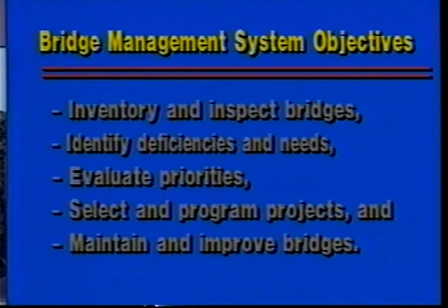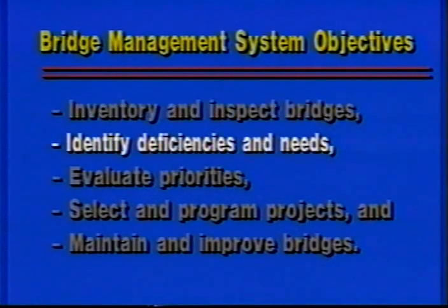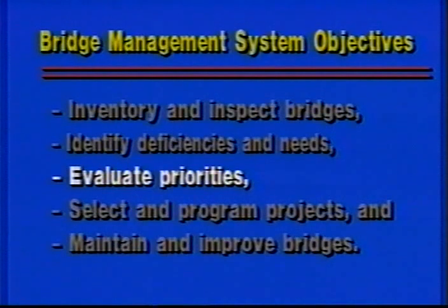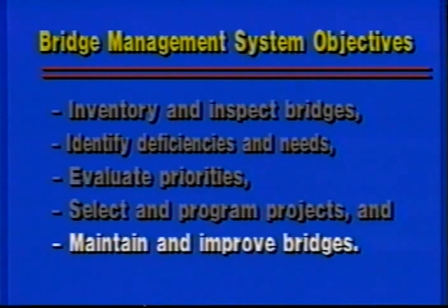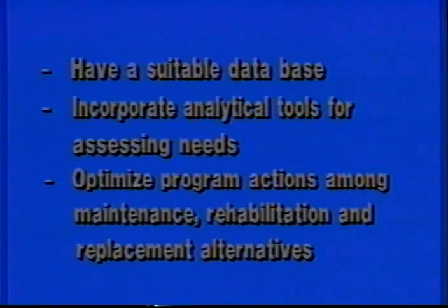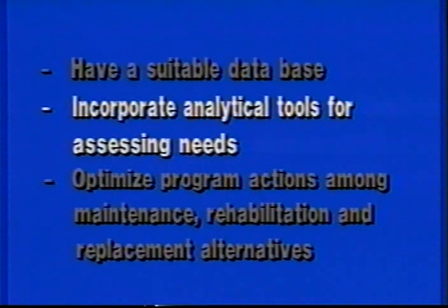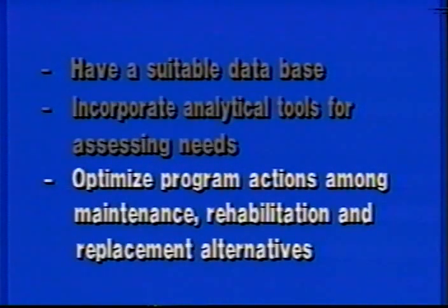A bridge management system formalizes the activities of inventorying and inspecting bridges, identifying deficiencies and needs, evaluating priorities, selecting and programming projects, and maintaining and improving bridges. Such a system should have a suitable database, incorporate analytical tools for assessing needs, and optimize program actions among maintenance, rehabilitation, and replacement alternatives.